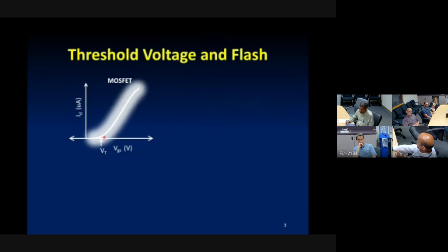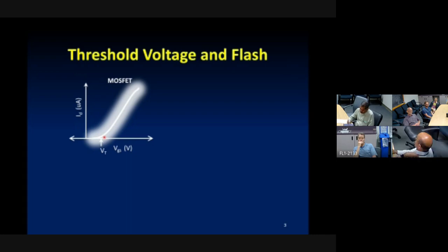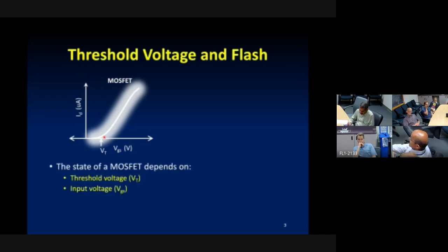Again, like I said in the last slide, because of all those variations, lithography and so on, this VT varies all over the place. When I fab a transistor, out of the several billion transistors in my iPhone chip, I can never predict what the VT of a certain transistor will be. There are all these variations among the transistors due to those effects, so the VT I get for one transistor randomly varies. There are some distributions that we have, but this is something we don't want. I'd love to have a single VT. Can I do that? That's the question.